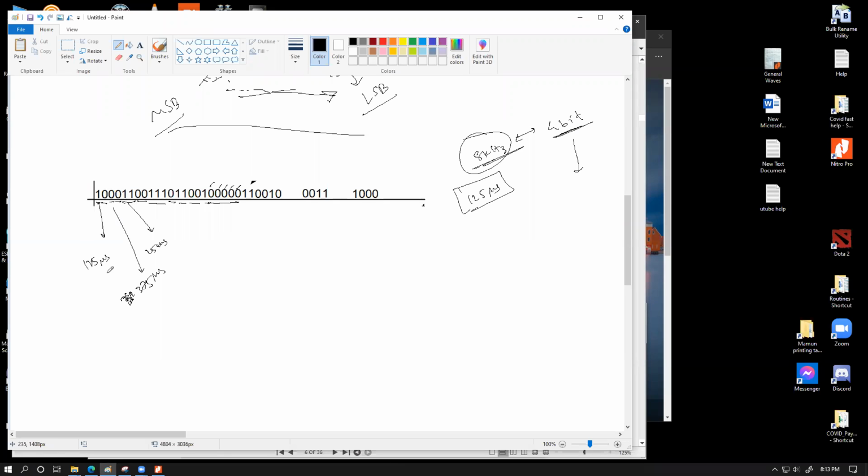So essentially it's going to observe the light sources or the voltage durations within multiples of 125 microsecond and convert them into bits, and then it's going to chop this entire stream of data into groups of 4.